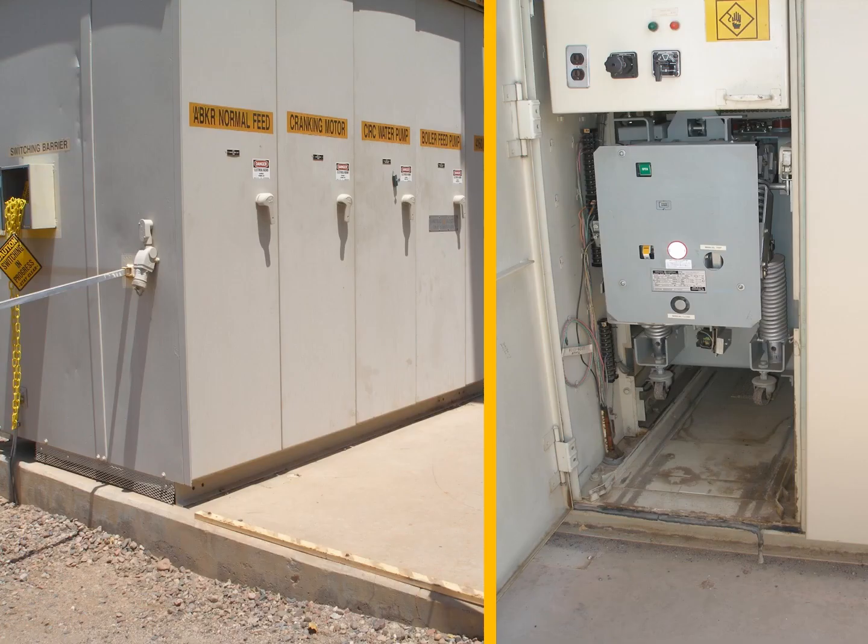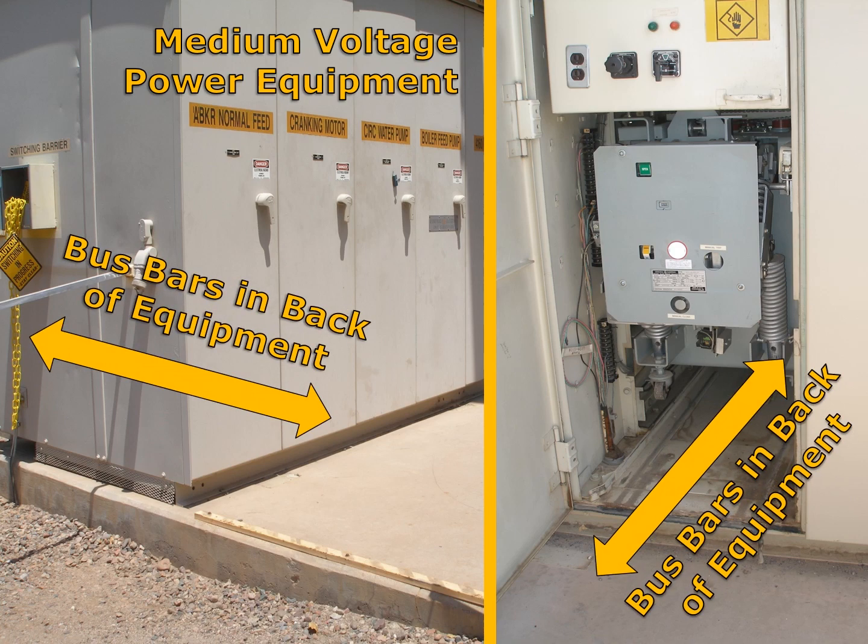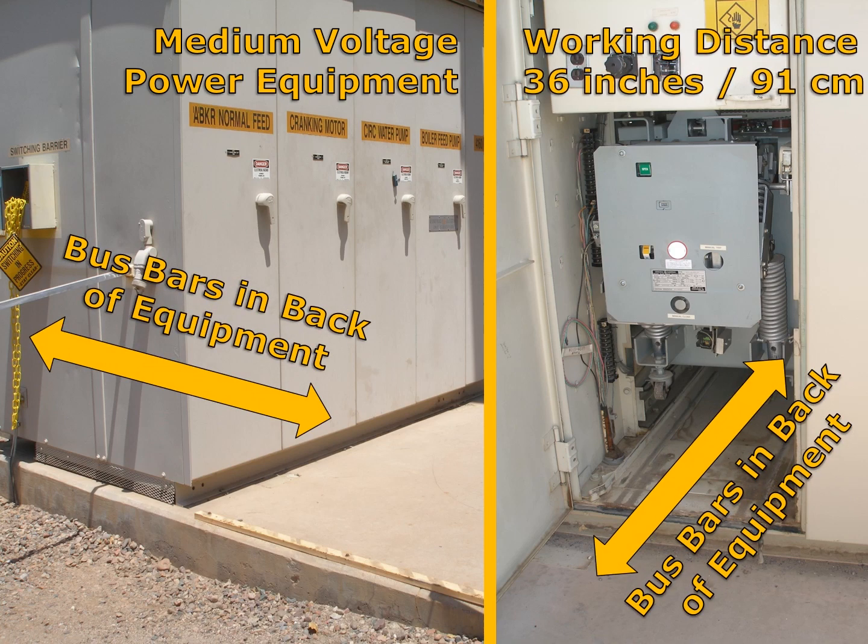For medium voltage equipment, such as 5 kV and 15 kV switchgear, the working distance is listed as 36 inches. For similar reasons as with the low voltage power equipment, the consideration is that any exposed energized parts may be further back within the equipment. Now, you don't have to use 36 inches. That's just what is listed in IEEE 1584. If you want to use a shorter working distance, you can do that. Just keep in mind that the calculated incident energy is going to increase dramatically.